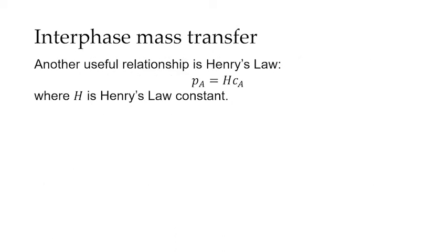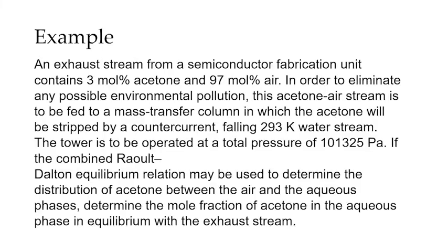Another useful relationship that we will be using is Henry's law. Henry's law states that the partial pressure of a certain species in the gas phase is directly proportional to its concentration in the liquid phase, and the constant of proportionality is called H, or the Henry's law constant. This is applicable for the dissolution of gases, wherein if you have a high partial pressure of a substance over a solution, then you will also have a high concentration in the liquid phase. Okay? We will be using all of these equations in our examples.